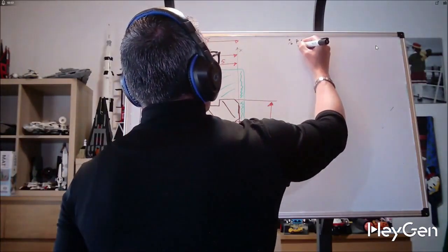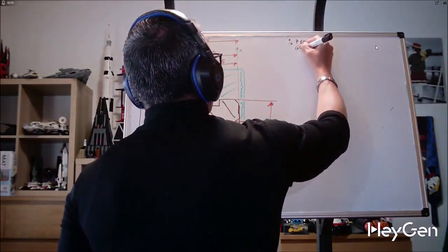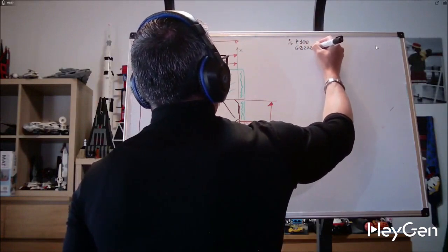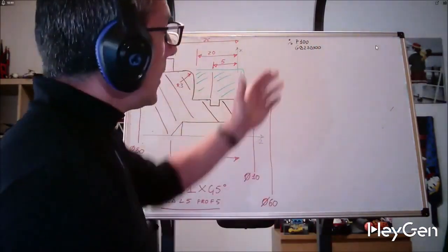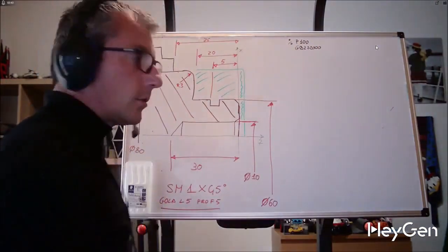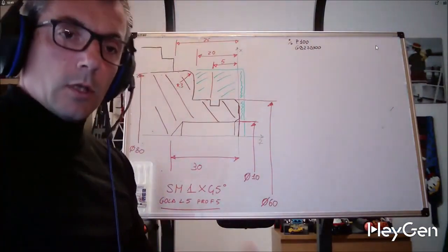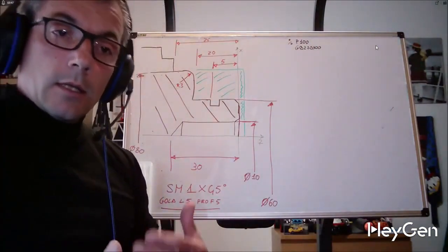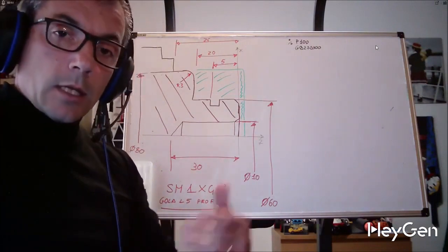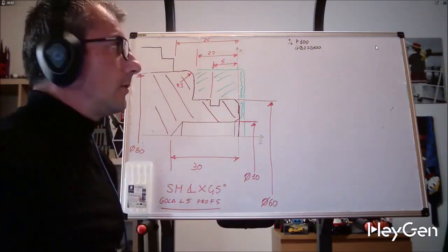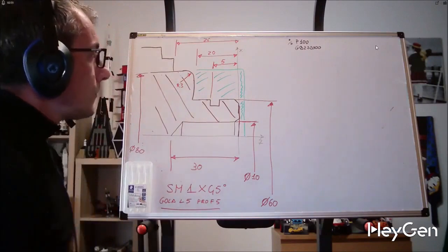First, we need to set G92 S2000 to limit the revolutions when using a simulator. Here we will also define our raw material to allow the graphics to work for us, becoming our eyes, and we will see it later in the simulator before making adjustments and avoiding unpleasant surprises.